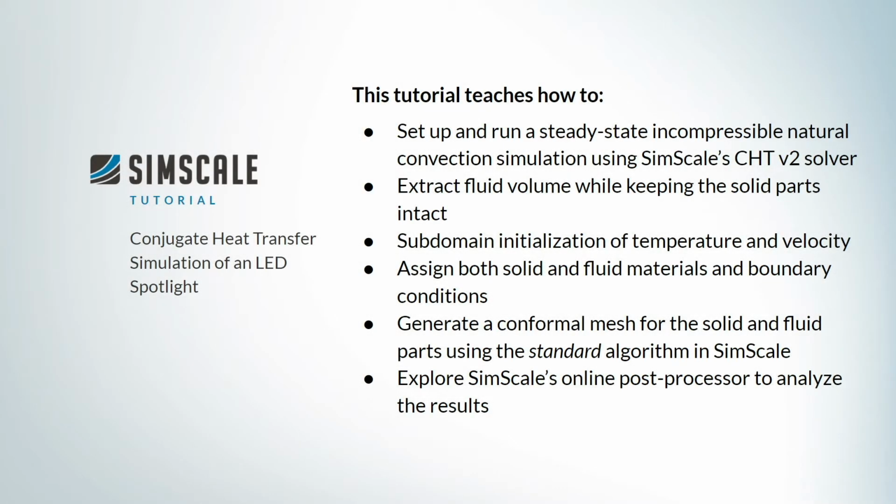This tutorial teaches how to set up and run a steady-state incompressible natural convection simulation using SimScale's CHTV2 solver, extract fluid volume while keeping the solid parts intact, subdomain initialization of temperature and velocity, assign both solid and fluid materials and boundary conditions, generate a conformal mesh for the solid and fluid parts using the standard algorithm in SimScale, and finally, explore SimScale's online post-processor to analyze the results.